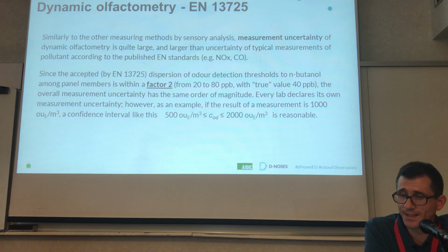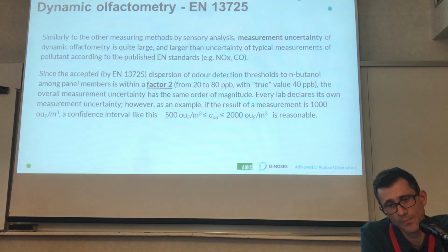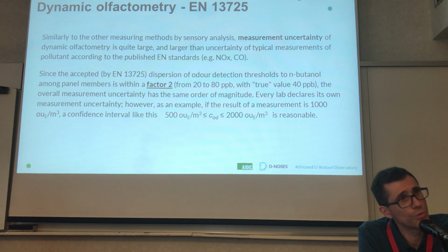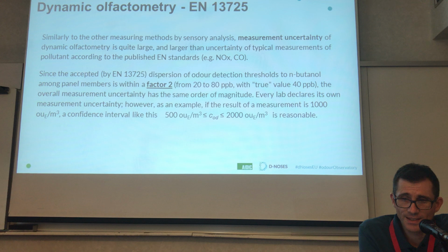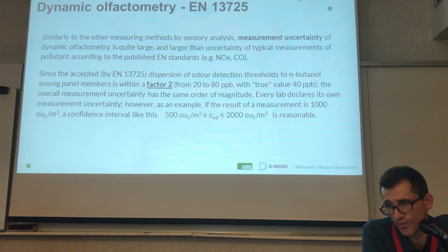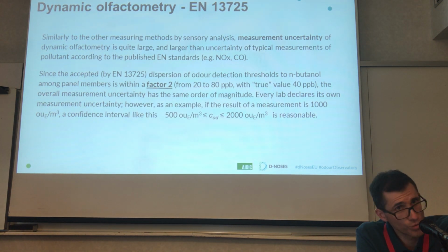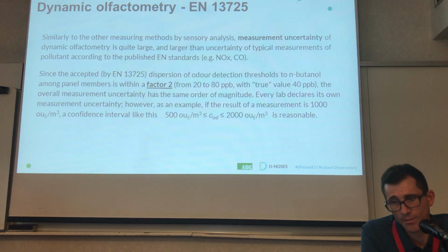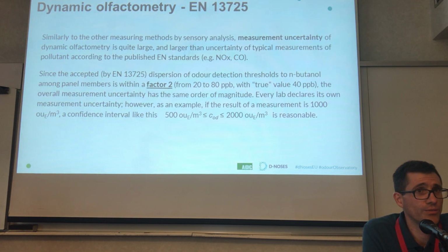But the standard defines, anyway, an acceptable window for the accuracy of measurement. Since the accepted dispersion of odor detection threshold to N-butanol among panel members is within a factor 2, from 20 to 80 ppb, the overall measurement uncertainty has this same order of magnitude.